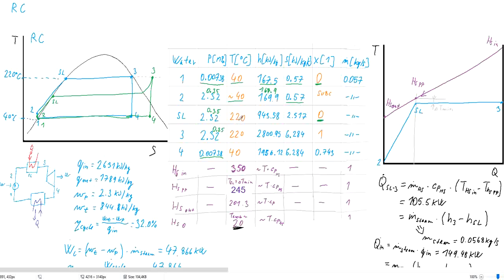For the temperature at this pressure, we can search for the saturation temperature for 0.35 megapascals, and we will get a value of 138.9 degrees C. And the enthalpy can be obtained also from some property functions from the quality and the pressure, or from the enthalpy at saturated vapor and at some specified steam quality, and again the linear dependency of the enthalpy with the quality.